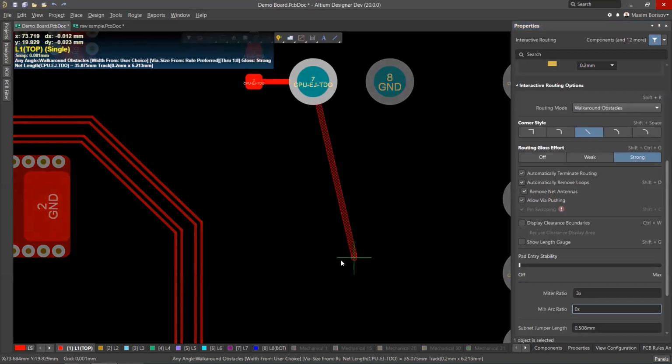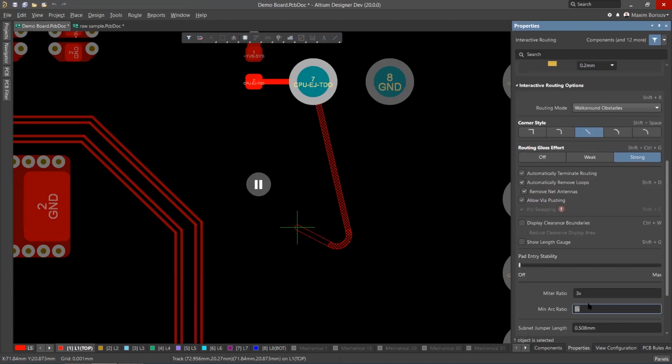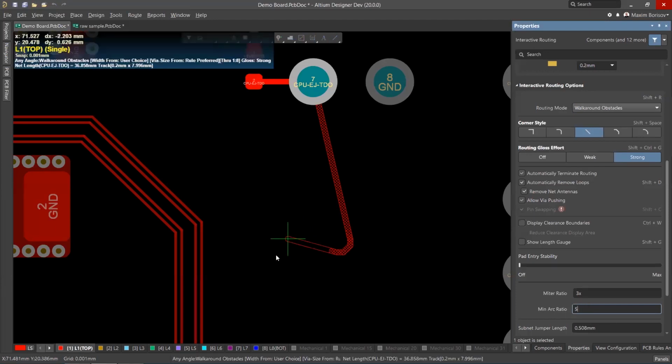If I put traces like that and try to run, let's say, free angle segment, it won't allow me to make a kind of sharp angle connection. It will maintain this kind of arcs. And even if I switch to lines, that will remain the same.